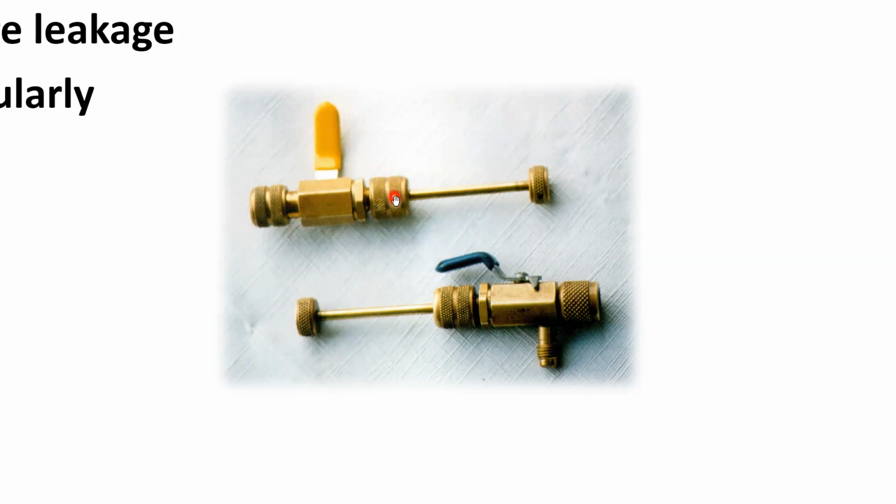and replace it under pressure. Prior to having this tool, we had to remove all the refrigerant out of the system and then weigh the system back in again. And when you're talking 50 to 100 pound systems, it's a lot of refrigerant you've got to remove and then try to put back in, and it's not conducive to a good environment.